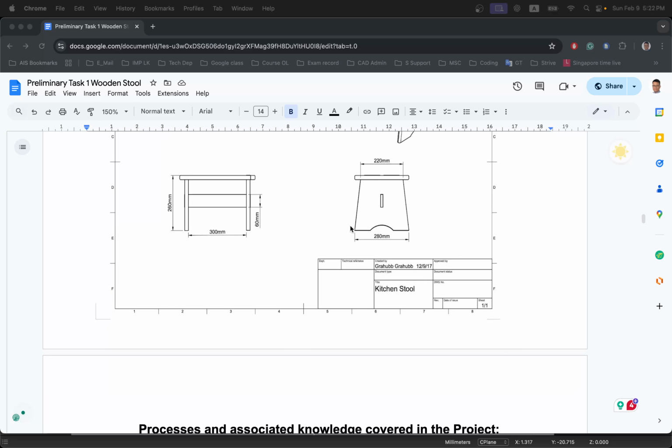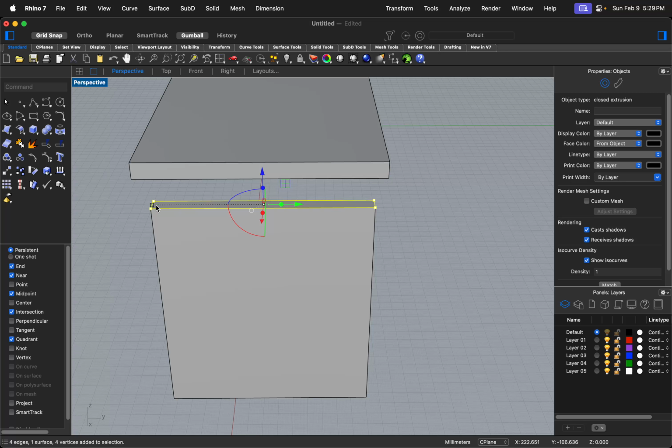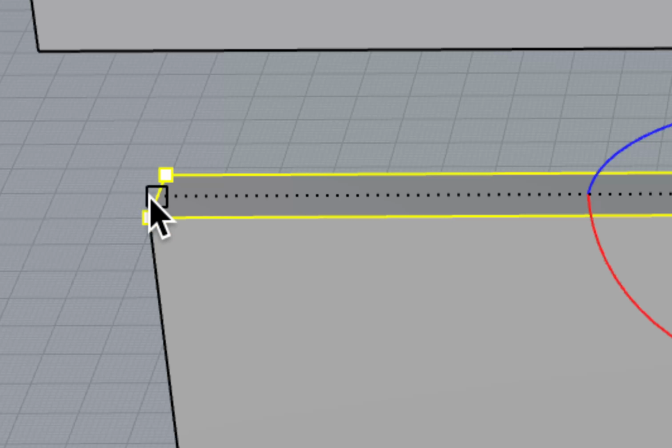Once you have selected the top surface, you can easily use the gumball, the scale function, where you can see the little green arrow, click and drag it inwards. In this case, I have created a 3D ring. When it's done, I will then observe and inspect if this is what I want, and I'm happy enough.